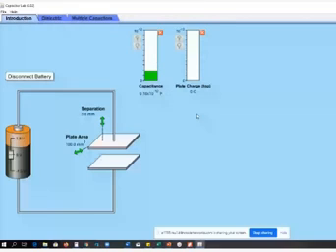And all you have to do, after you have been able to set this properly, is to record the value of capacitance you have here. What value do you have here? Can I hear you? 0.18 times 10 minus 12. Good. Times 10 raised to power minus 12 stands for what? Pico. I said that earlier. Pico is 1 times 10 raised to power minus 12. So you can either record it as 0.18 times 10 raised to power minus 12 farad, or simply say 0.18 picofarad, whichever one pleases you.